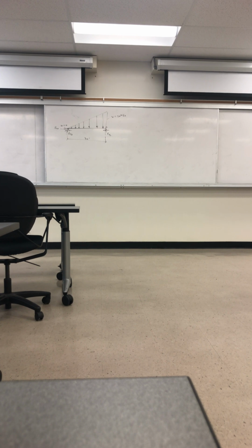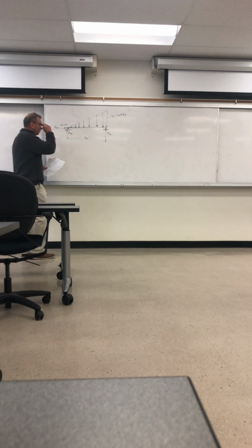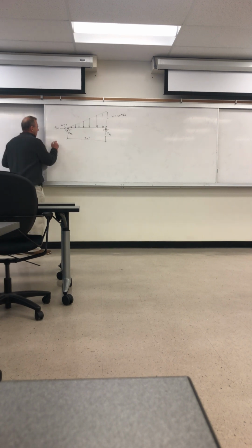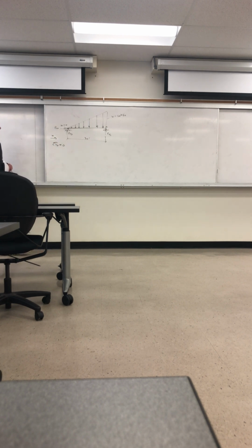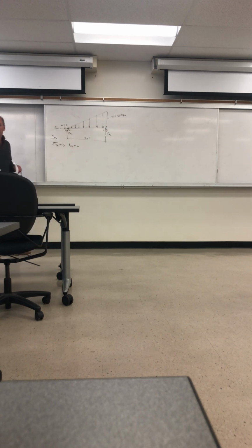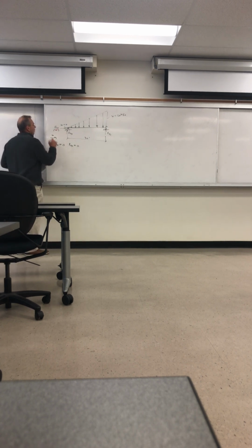So we saw this last time, and we integrated. Now we're going to solve for the reactions without integration. As far as the longitudinal direction, it's the same as before. We have the summation of forces in x equals 0, this being x, the horizontal direction. So R sub Ax must be 0 because there are no other loads and no other reactions in that longitudinal direction. That's what we found before.